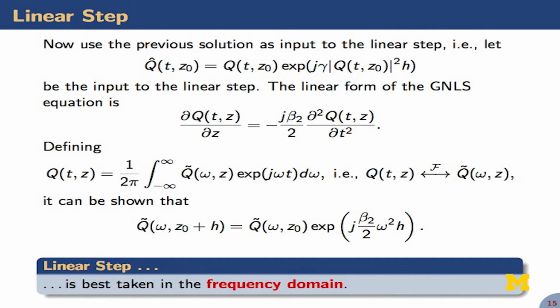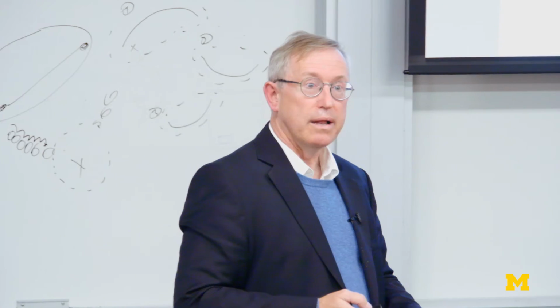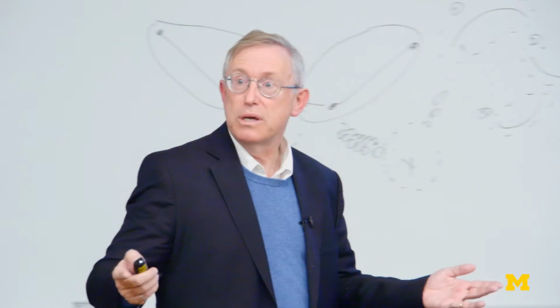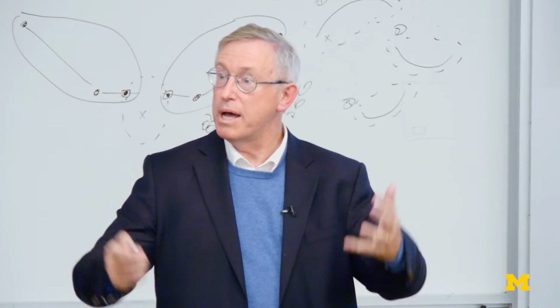So if we didn't have dispersion, we could do this nonlinearity in the time domain. It would be very easy to do in an implementation. If you flip things and turn off the nonlinearity and turn on the dispersion, then you have a linear differential equation, and so you have an LTI type linear system. And you know that the best way to tackle an LTI system is in the frequency domain, right? So take the Fourier transform and multiply by a filter.